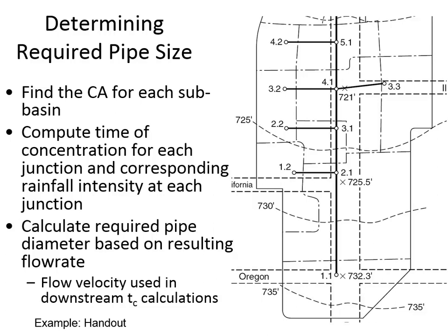And so on the second page of the spreadsheet, what is provided to you is the name of each pipe. On the printout I've given you, the pipes are labeled as pipe A, B, C, D. On the figure here on screen, they're not labeled in the same way, but what you need to do is fill in the blank for the upstream junction and the downstream junction. The contributing area has already been defined for pipe A. So here it says, for example, 2.2 acres is the contributing area that goes into pipe A.